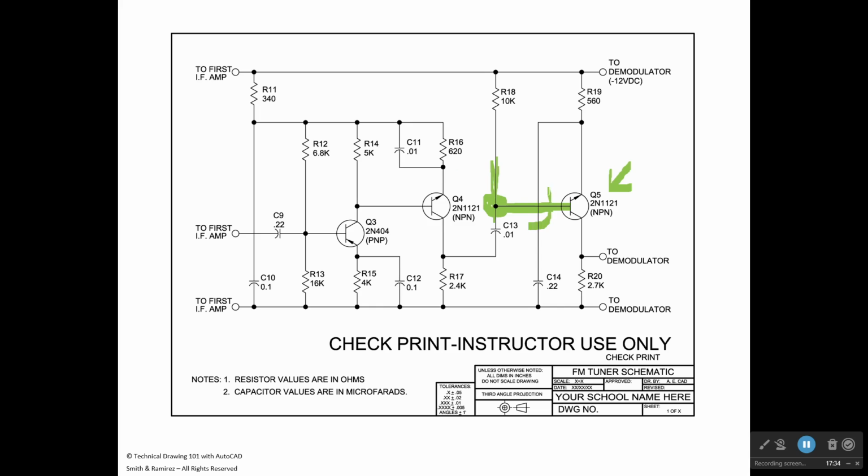But look right here, there is no dot. And what that means is that those lines are not connected electronically. So they are insulated to each other in some way. It could be that this is a printed circuit board, and so the conductor could be on one side of the board, and this conductor here could be on the back side of the board, or a different layer, so that they don't touch each other. The moral of that story is don't put a dot right there, or it would indicate that they are connected.